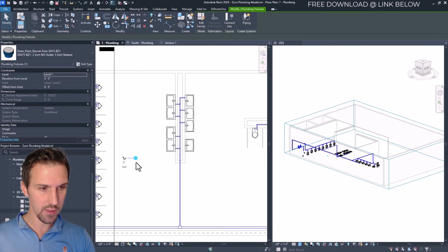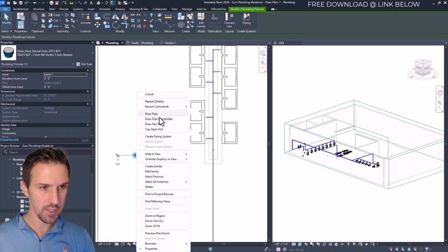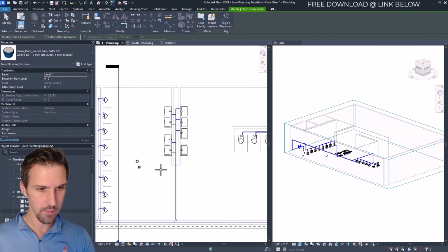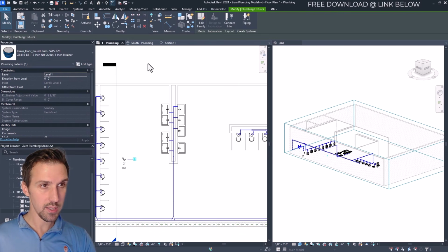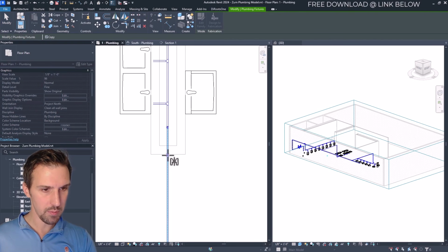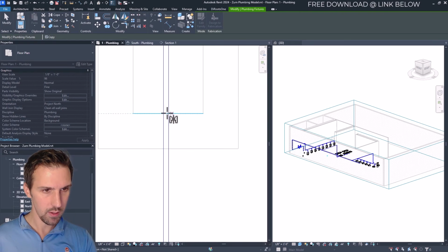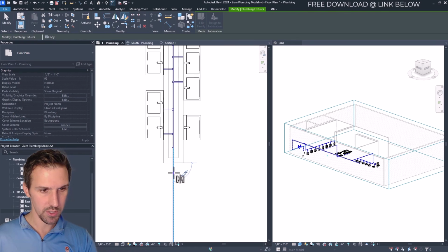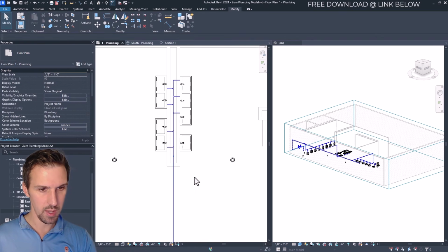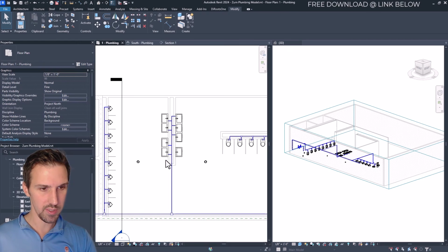So I'm going to go ahead and click on this one, and we're going to right click. We're going to say Create Similar right here. And we'll put another one maybe on this side of it. Now it would be kind of cool if I just mirrored that. So let's do that. I'm going to click on this guy. I'm going to click this Mirror, Pick Axis, or let's Draw the Axis. So I'm going to click on that, and then let's draw it from this midpoint of this wall right here. Now we can't really click on the midpoint. So maybe we'll just do it to this point right here. And we're just going to draw this axis to here, and boom, it puts it right in the middle, or the same distance from here as to here. So that looks pretty cool.